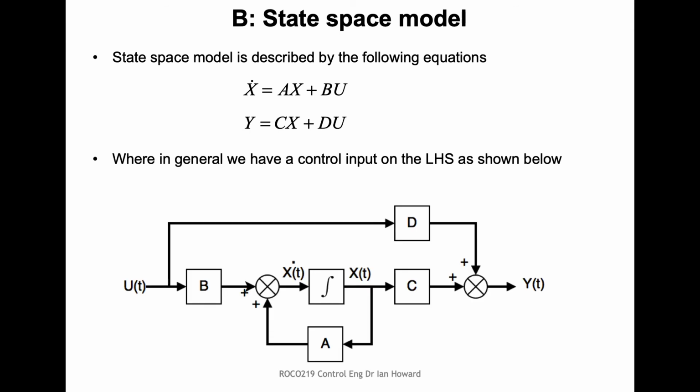We then want to write that down as a signal flow graph. If I was drawing this, I'd start off by writing down the x dot and the x. First of all, to get to x from x dot, we need an integrator block. So we integrate x dot, and we end up with x.